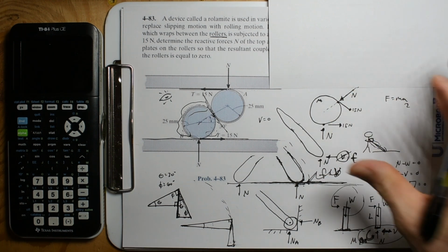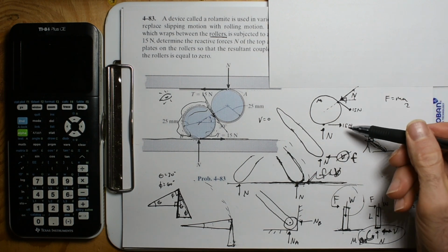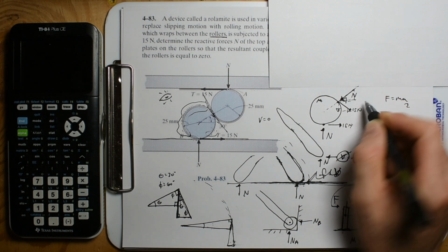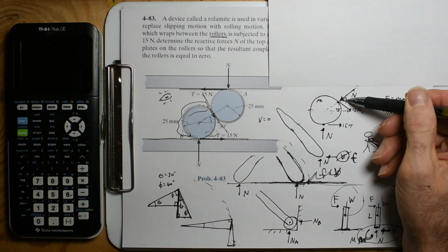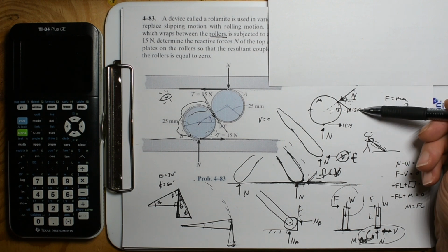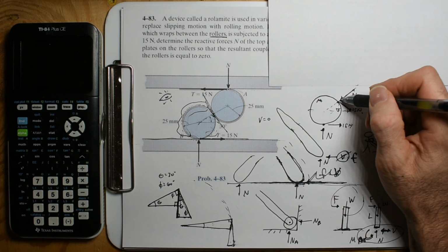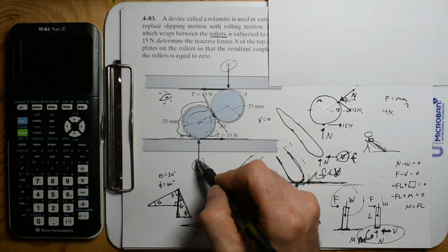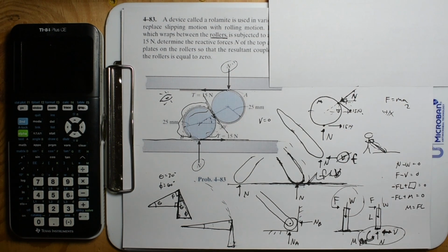A lot of these are going to duplicate each other, but this is the only one that actually has a component in that direction that can balance those two. This force has a downward component and a component in, let's say, the positive x direction. And so this portion of that force is the only thing that can balance this and that. So now you can see that this normal force right here is going to be quite high. And I'm just saying all these are normal forces. You would want to label them different things so you're not mixing up this end for that end.